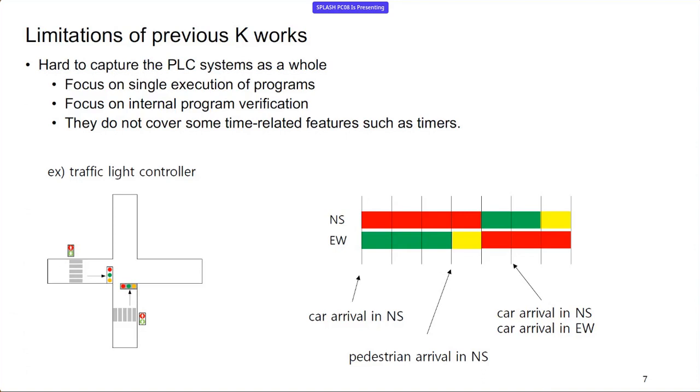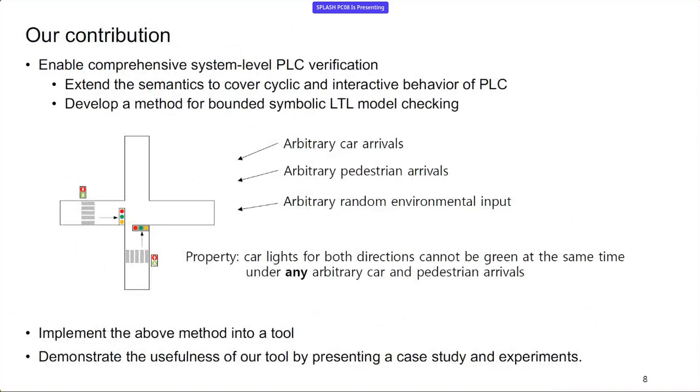Our contribution, in short, enables comprehensive system-level PLC verification. We did that by extending the semantics to cover the cyclic and interactive behavior of PLC, and then we developed a method for bounded symbolic LTL model checking.